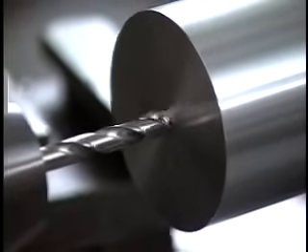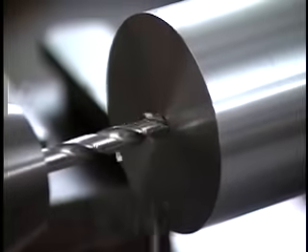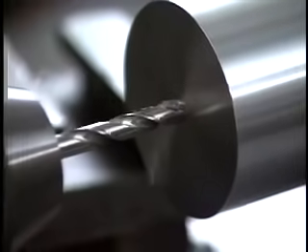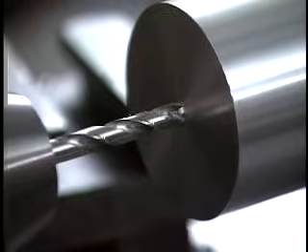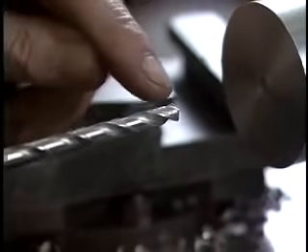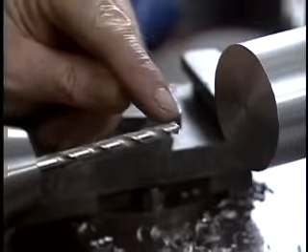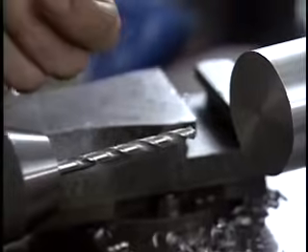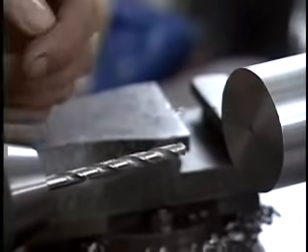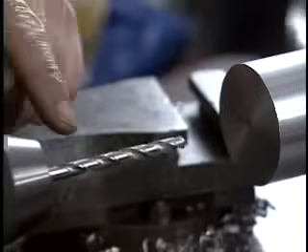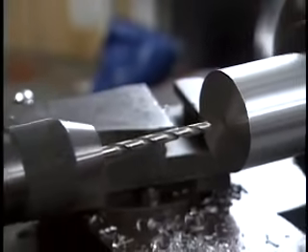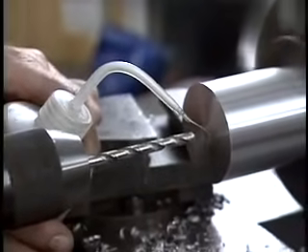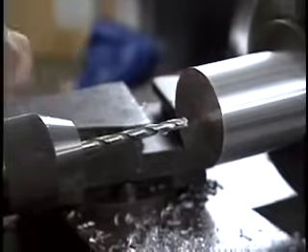The first pass with the drill, I'm going in about 4 or 5 drill diameters. You can hear now a squeaking sound. That's being produced by the drill and the chips, because the chips are having a very difficult time riding up through the flutes of the drill and out of the hole, and are starting to bind in the hole and producing heat and chattering. So now that I've drawn the drill out and cleared the chips, before I go in again, I should introduce a little bit of cutting fluid into the hole and onto the drill.